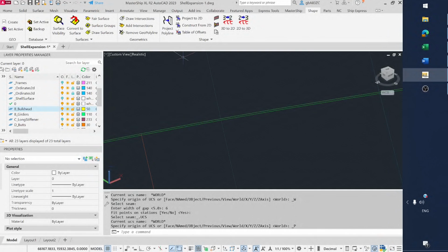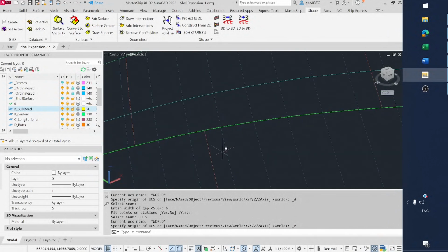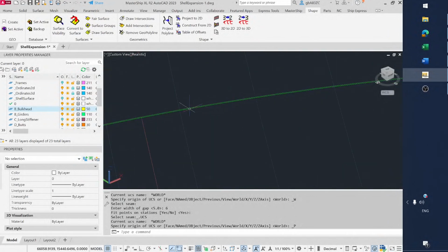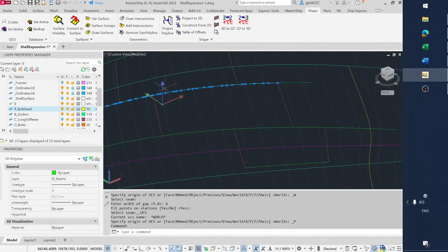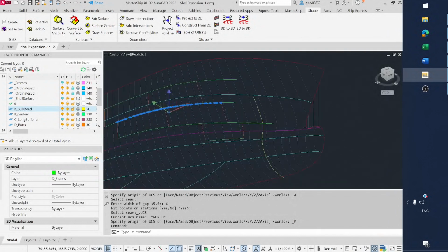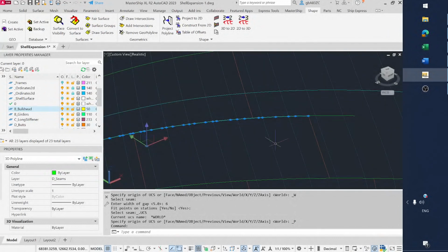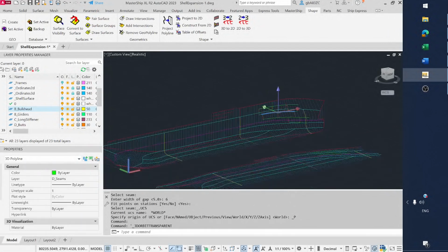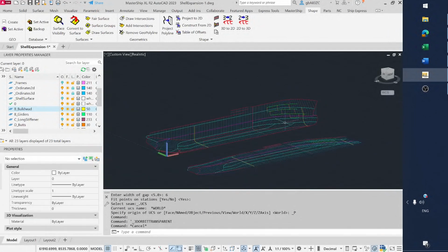And we could also do it, of course, up, and we can do that for any line in the model. So this adjusted line is maybe not something you want to transfer to the arrangement, but that you would use to make your 3D hull plate expansion. There's more about hull plate expansions in other videos.